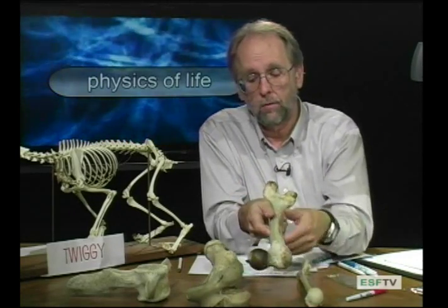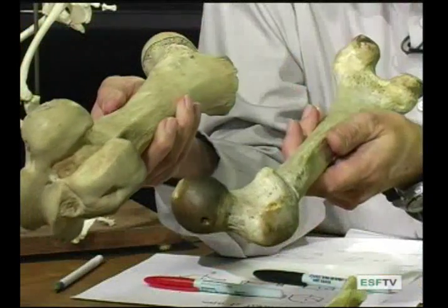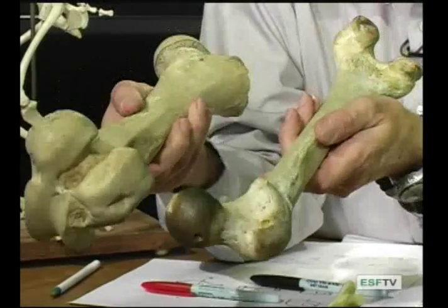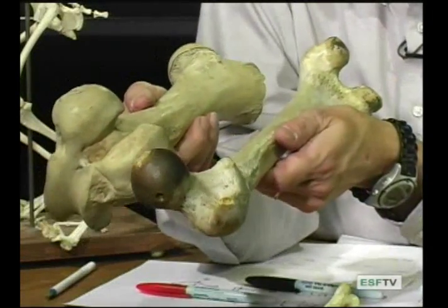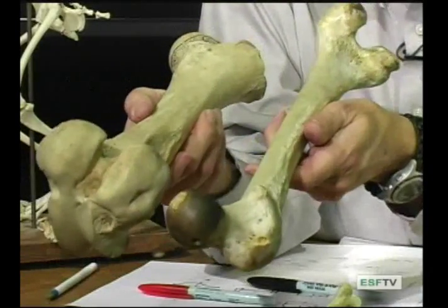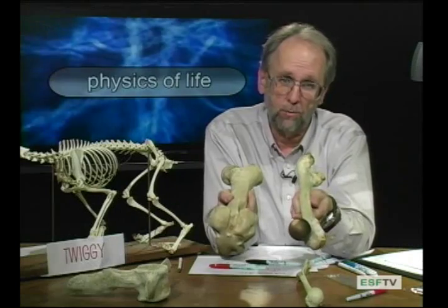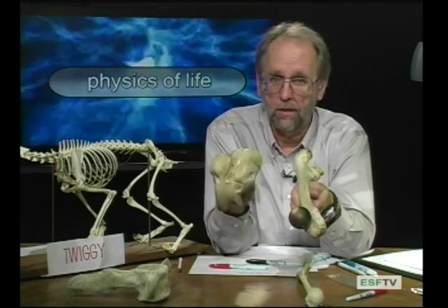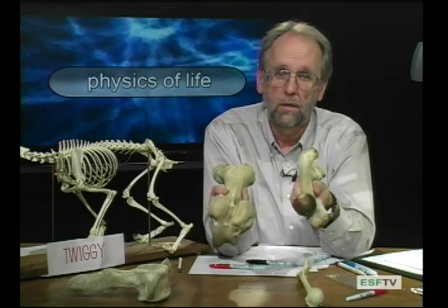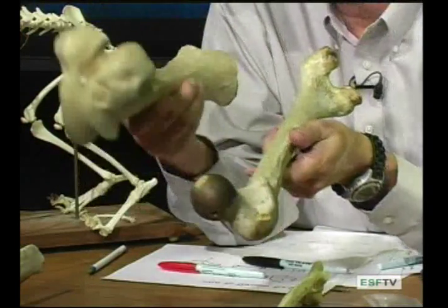And of course, we can compare these two bones here. This is a femur of a cow, and this is the femur of a human. Obviously, cows have to sustain much larger loads. The length of this one is shorter, but not that much shorter, but the diameter is quite a bit different. Again, the second moment of area in the cow femur is going to be much greater than in the human femur. And again, the same material characterizes both, but what's enabling this bone to hold up a cow and this bone to hold up a human being relates to the shape of the bone, namely the second moment of area of the cow femur versus the human femur.